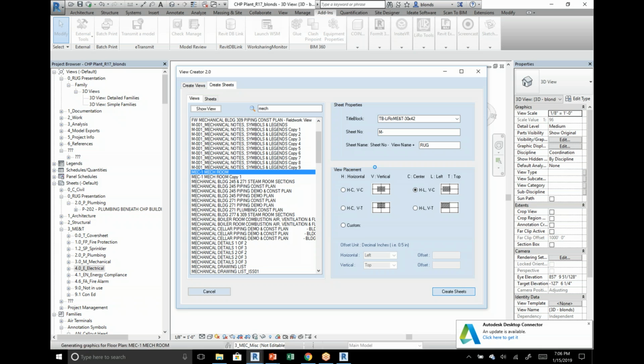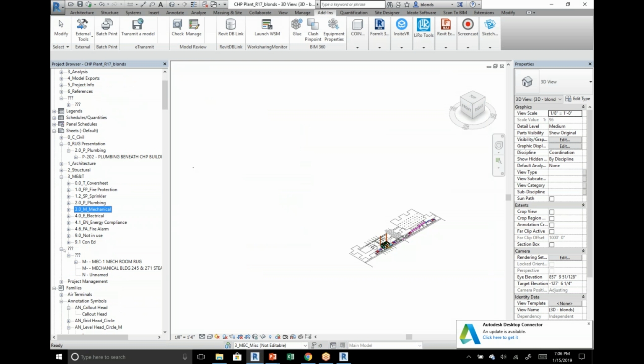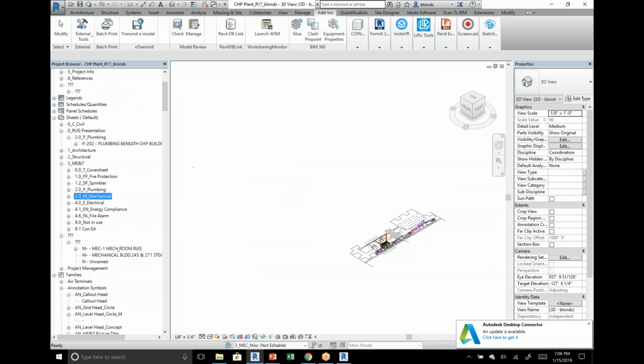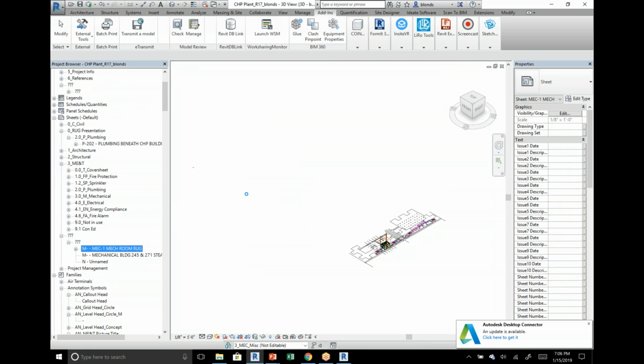But then for bulk renaming, having a separate plugin, again, either third party or in-house or whatever's available to you, that brings it to Excel. Way easier to rename and renumber things in Excel than in Revit. Because again, Revit, even using a schedule, which is more effective than doing it line by line in the project browser, it will take time to reload and refresh each time. Here we go, that's complete. Looking for the next one. So let's go down here to the question marks. And here it is. So this is the sheet we just created. And we should see how that's scaled actually.